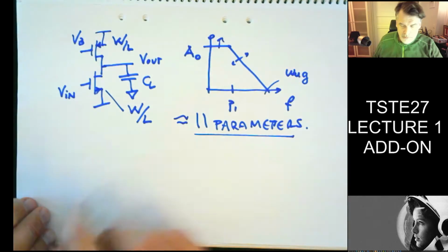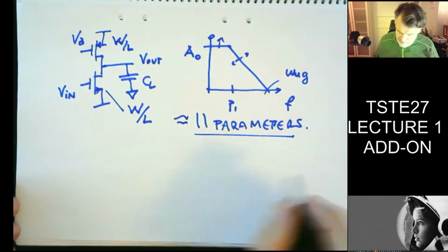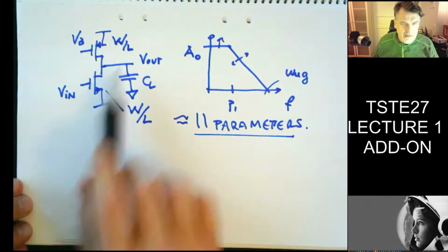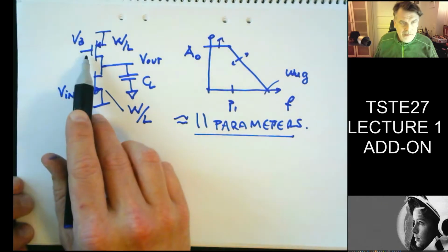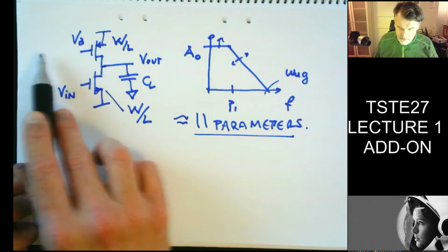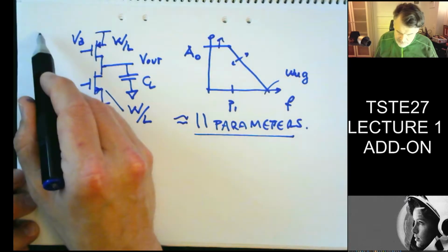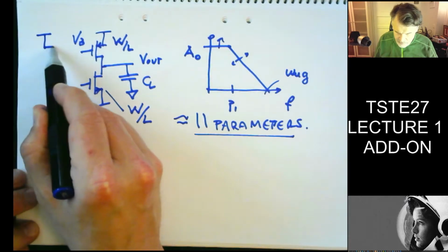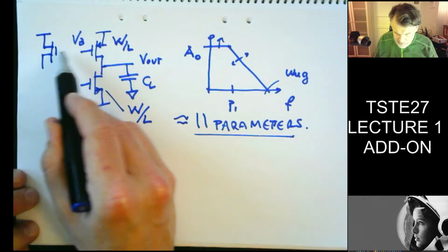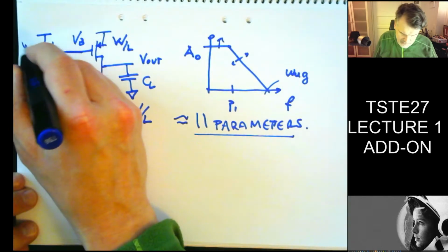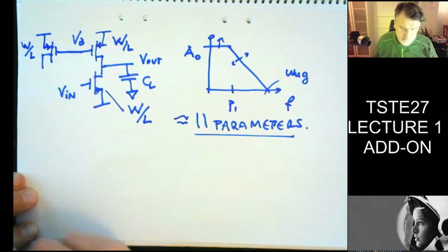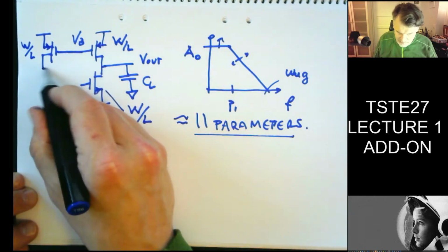However, before we do that, this is our basis, and we can eliminate some of these parameters by adding a quite clever help circuit on the left here, which we refer to as a current mirror. So I take a PMOS with the same size as this one, like that, and I connect it like a diode.